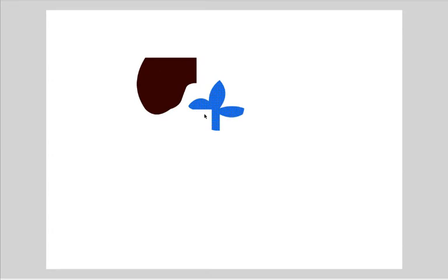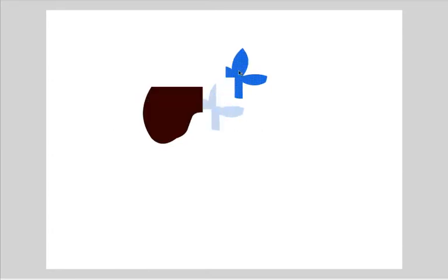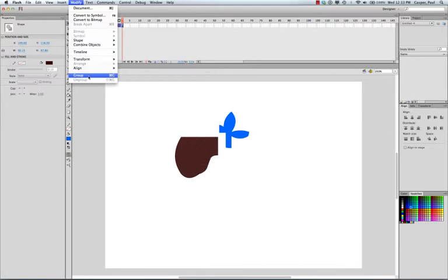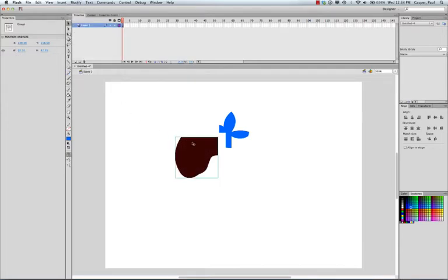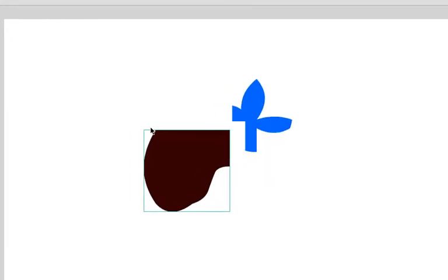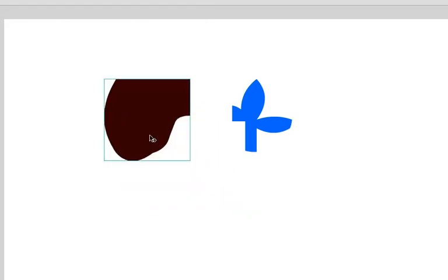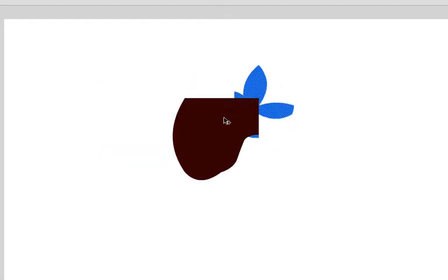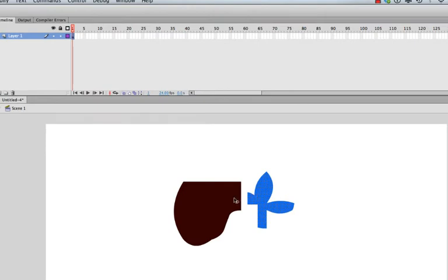If you want to stop shapes from overlapping and taking pieces and merging from each other, you can simply select each drawing object individually and group it with itself. So I'm going to select what used to be the square, go to Modify, Group, and once I group that merge object with itself, it now has a bounding box around it and it's protected. When I select it, you don't get that grid pattern. When I try to overlap it and move stuff, things are safe.